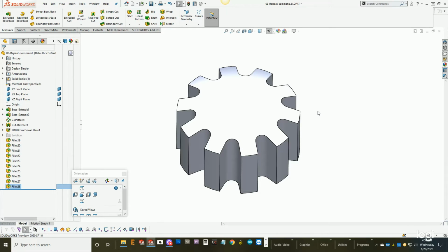Okay, so I finished up all my full rounds, and you're probably asking, Mark, why didn't you just build the full round into your sketch and then extrude a profile? Yes, of course, you could have done that, but there are a lot of cases in models that are more complex than this that you don't get that option, that you have to actually apply full rounds, especially on more complex geometry that's just not an extrude.